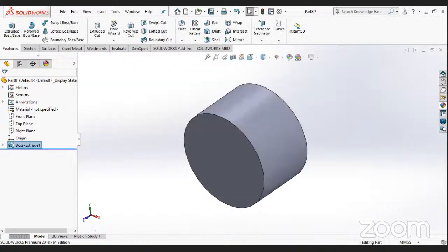You can see that this part is hollow. So we need to also cut the part till inside, and the thickness of which you can see here is given 8. So 8 mm is your thickness, I suppose. No, you can see from the top view, this is the upper part, which is the outer one, and this one is the inner circle.